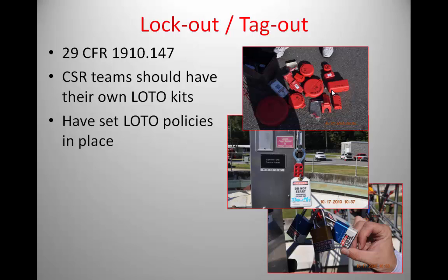And a real quick breakdown of how that works is the first in company will put their lock on it. Our hasp, our lock, our tag, and if it's a first in engine, you can use yours. If it's Rescue 1, we prefer to use lock number 6. As you can see noted in the picture, each of the Rescue 1 locks are numbered, and on each lock is a key, and then there's a key ring in the lockout tagout kit that has keys to the individual locks themselves. So first in gets there, will put their lockout tagout system in place.